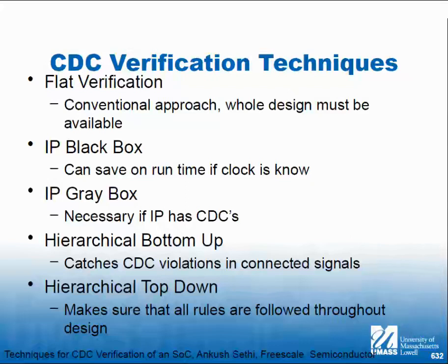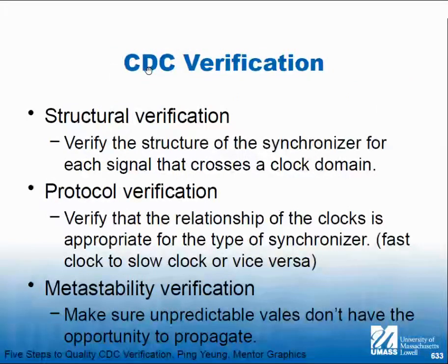So every clock domain crossing, no matter what the designer thinks, has to be fixed. And my response is, hey, we're not going to take that extra flip-flop out of your pay. So structural, right? Make sure that every place you blindly put in a synchronizer, that would be my first one, the highest priority.